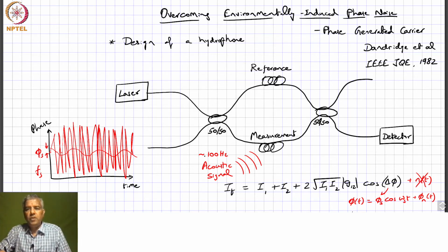And we know that when you are looking at that low frequency signal from your optical receiver, you have 1 over f noise, because finally you are picking up intensity corresponding to this phase change. So, all this 1 over f noise will come into the picture, and so that is going to be a huge component. So, if at all possible, you want to shift this measurement frequency to some other higher frequency, okay.